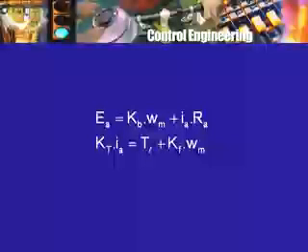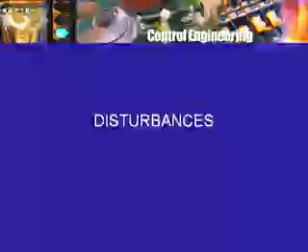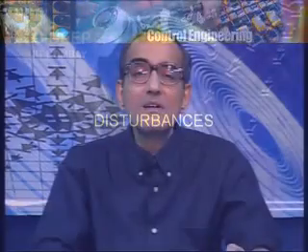These are the two things that one normally worries about. One is the input voltage, the other is the output requirement, the torque, and I used earlier the term disturbance, although for TL it is not really disturbance, it is the main reason for the drive, but EA, changes in EA can certainly be thought of as disturbance. The power supply voltage was expected to remain constant at 230 volts, but it has not remained so because of some disturbance, some load, whatever.